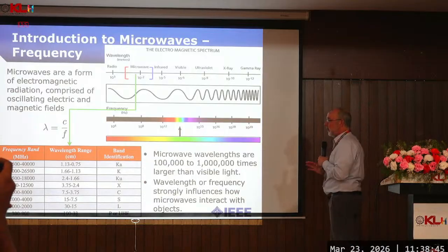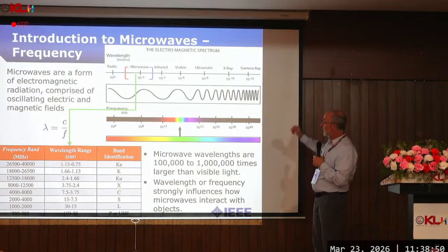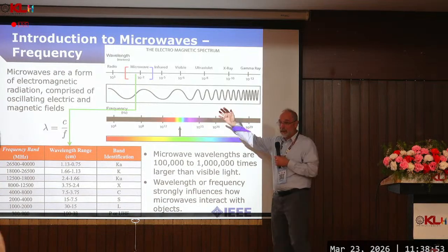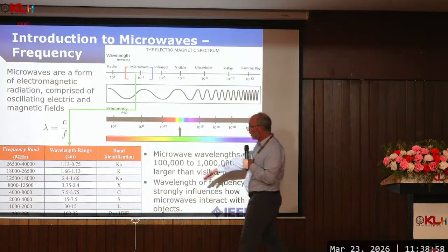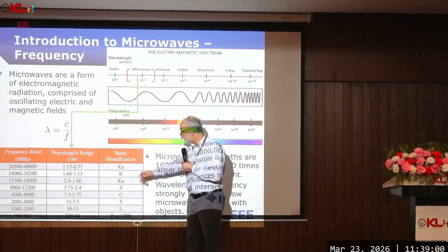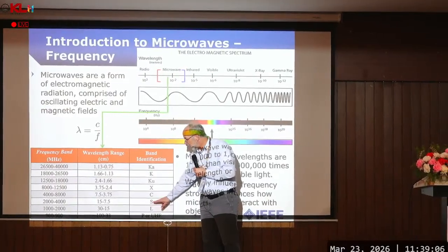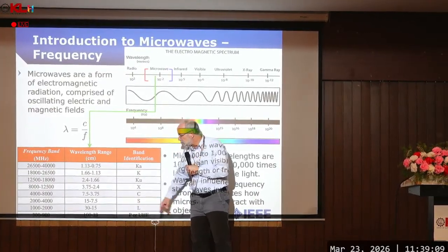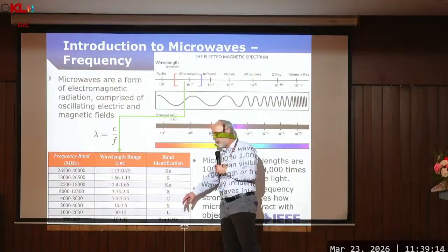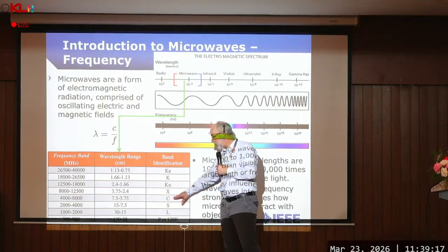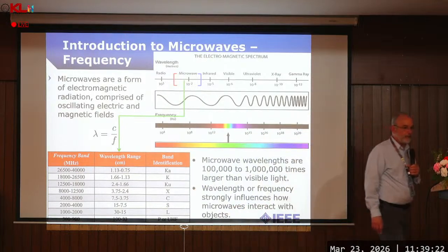We typically operate these radars in microwave frequency ranges. There's the spectrum that you're all familiar with. Microwaves are in the centimeter to meter to millimeter range. And these are the typical operating frequencies of radars. NISAR is operating at L band, which is 24 centimeters, and at S band, which is, in our case, 9.4 centimeters. But there are many, many other radars I'm sure you're aware of. The RISAT mission from ISRO is at C-band. Many X-band satellites are commercially available now.